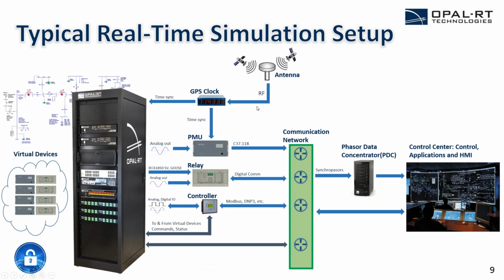And one of the main benefits to this model-based approach, since you are modeling your power system using software, you can actually implement what are essentially virtual devices within your model. And considering how costly it can be to purchase hardware, especially if you require dozens of, say, phasor measurement units, this is actually a very nice solution, especially for professionals that are concerned with the higher level applications and communication networks.